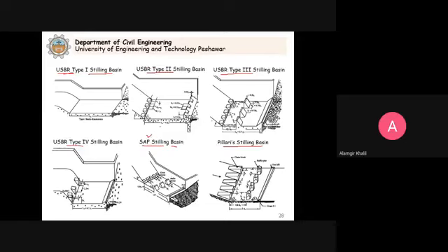The idea is, you can see here, they are made of concrete. The idea here is to initiate the jump, to dissipate the energy, and also contain the jump. This way, the destructive energy of the fast moving liquid will be destroyed, and it will not pose greater damage to the channel bed, and ultimately this will increase the stability and protection of the hydraulic structure.